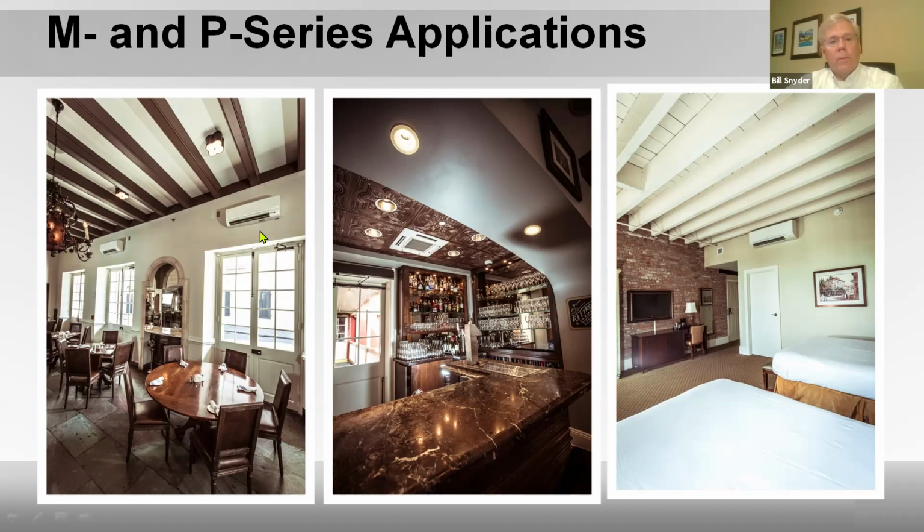Also, you'll notice these are up high enough. This has got to be a 10-foot ceiling, I would guess, in this commercial application, because right above doors and windows, there is a header that gets put in there. That's typically 2x10, 2x12, depending upon the span, but it's thick and tall, and probably not the best thing to drill through, because that actually helps support the roof.